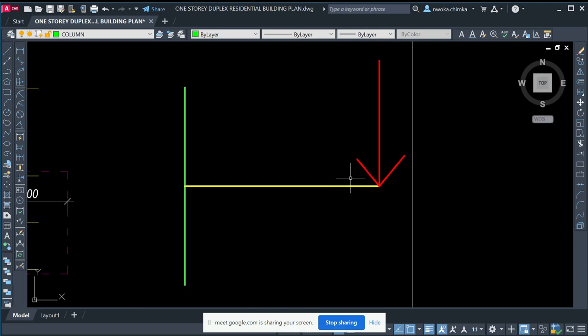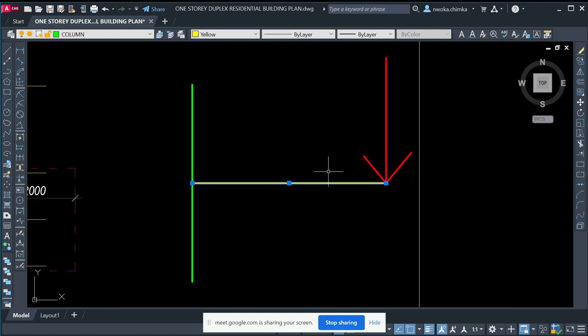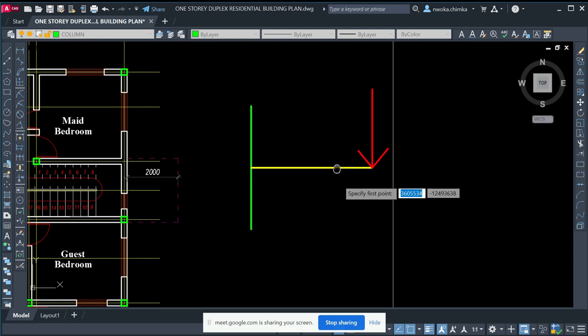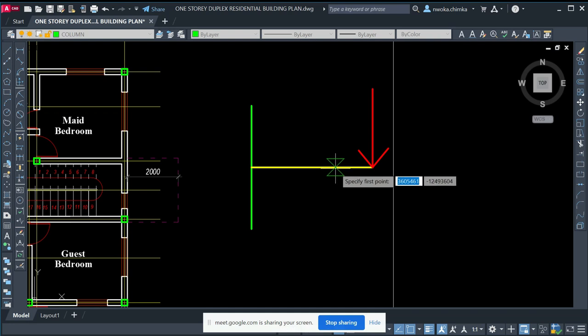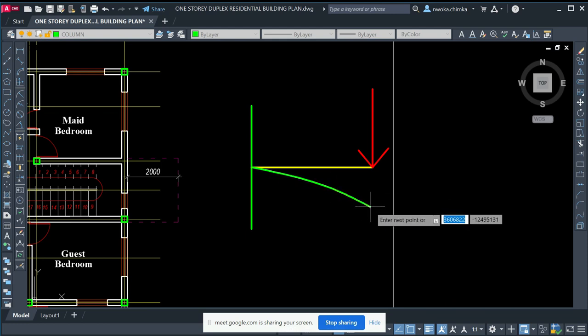So with this right now, if this cantilever length is very long, let me say up to 2 meters, 3 meters, 4 meters, I've done one of 6 meters before. What happens is that if there is no column in this place to support this cantilever and withstand all the moments coming from it, and you have only a beam, it will make this beam twist. When the load bounces on this cantilever, the moment looks something like this.